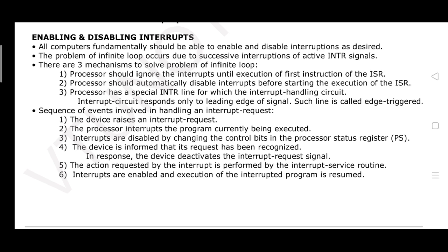One is that the processor should ignore the interrupt until execution of the first instruction of the ISR, the interrupt service routine. The processor should automatically disable the interrupt before starting the execution. Of course, this is a must. The processor has a special INTR line for the interrupt handling circuit. So there are multiple ways to deal with this. You will understand that because handling of multiple devices is the next topic. We'll see that topic in the next session.